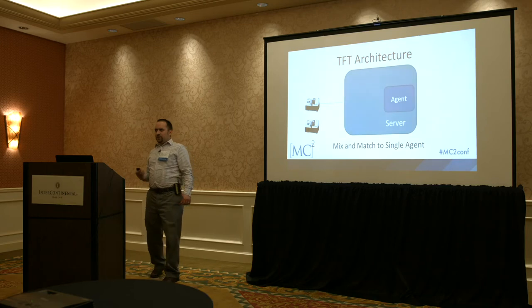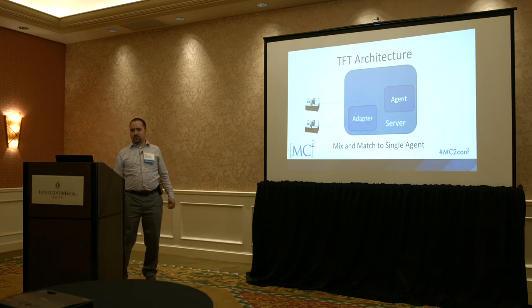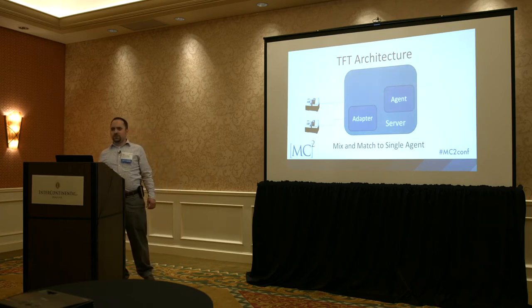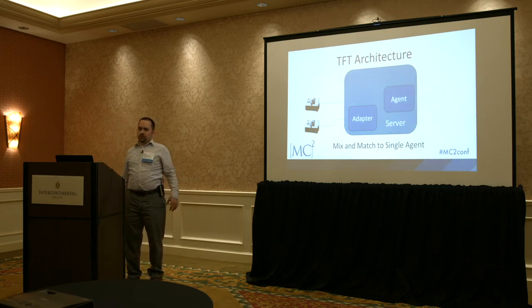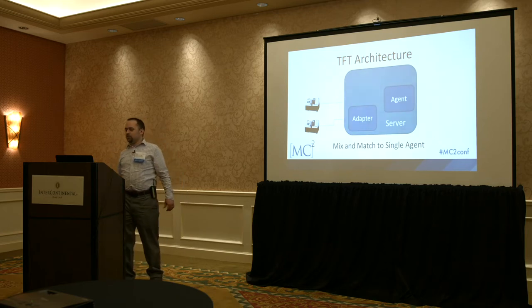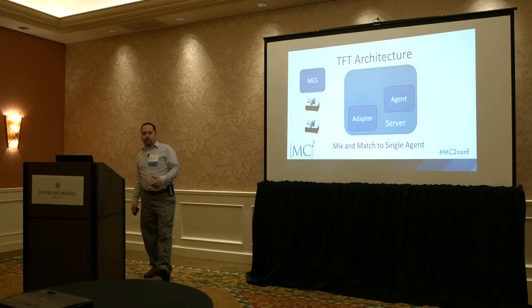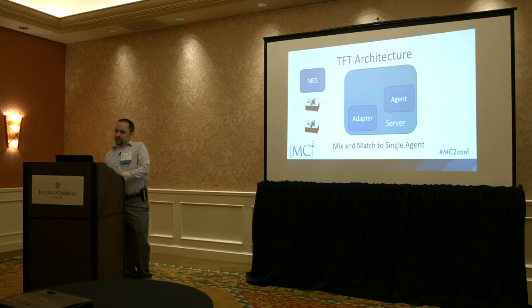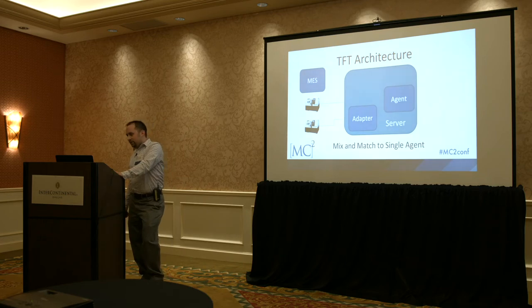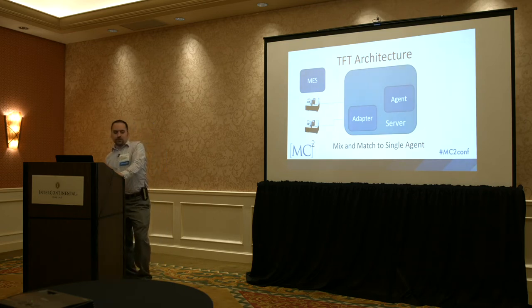Some of our machines have Ethernet-based adapters, and so the adapters reside on the server alongside the agent. They still are separate adapters, even though they're on the same server, because we're maintaining that architecture so we can plug all these different pieces together and get this mix and match. And then what we did, and what we've seen a lot of people do, is we wanted to supplement the data stream with things the machines didn't know, which is the operator currently running the machine, the part number, the operation number, if the machine's in setup or if it's down for whatever reason. These are all things that our operators know, that our operators are inputting into a client application they have. And so our MES is managing all that. And so we put an adapter on the server that pulls that data from our MES and converts it again into something the agent can understand.